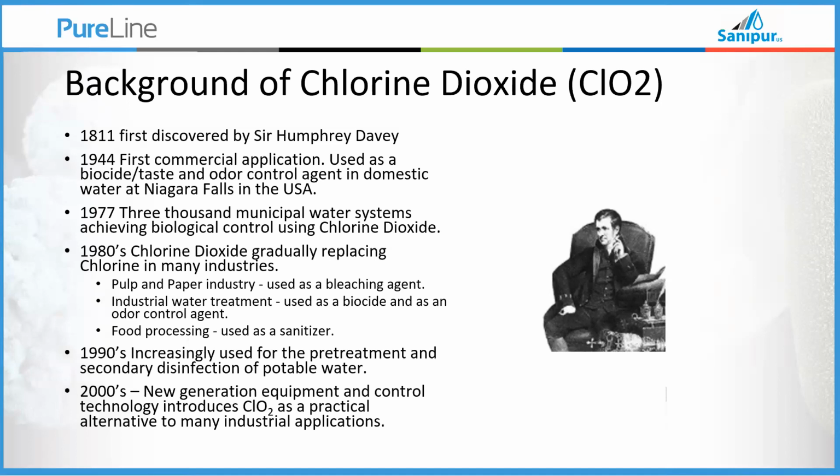By the 90s, secondary treatment, as I call it, in hospitals, nursing homes, hotels, facilities, started to really become a big thing, especially in those areas where the water quality coming to them wasn't as good, or the plumbing systems were a lot older, a lot of iron scale and stuff that really promotes the growth of bacteria.